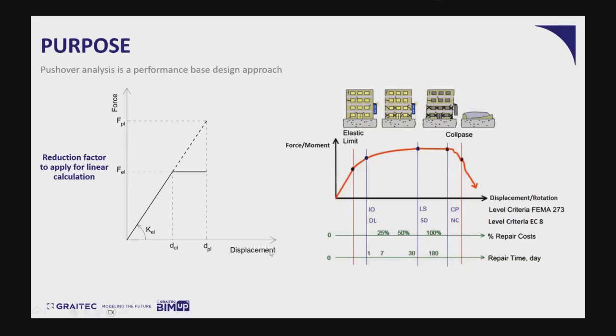Instead of going into nonlinear analysis, into plasticity, instead of having the full load applied on the structure in the elastic domain, since we know that the structure cannot go that far in loading because it has the elastic limit, and once this limit is reached we will have plasticization in the structure, we apply a certain reduction factor on the load applied on the structure. In this way, we can stay in the elastic domain of calculation, and this is easier for calculation.